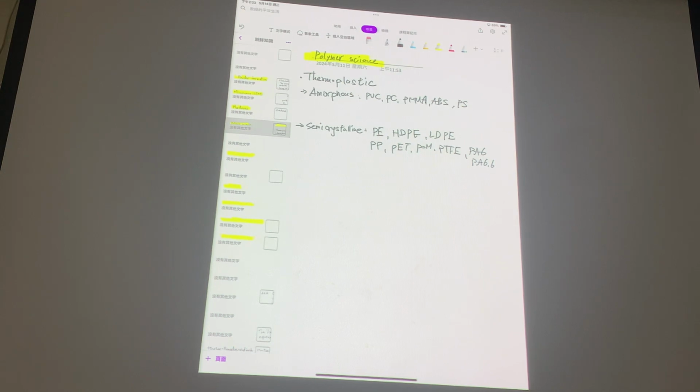It's actually relatively low, about 5 or 10% crystallinity. So when I say semi-crystalline, it actually has only about 5% or 10% crystallinity, which is already quite a lot. Mostly when we deal with polymer materials, they are amorphous, meaning non-crystalline, right? Another non-academic way to determine if it's not semi-crystalline but amorphous is to see if it's transparent or not.